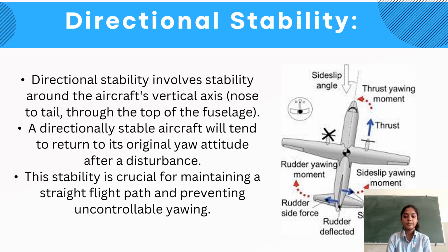To maintain directional stability and prevent the yaw from turning the airplane uncontrollably, the pilot deflects the rudder to the right. This creates a side force, countering the asymmetrical drag and the yawing moment from the engine failure. Directional stability ensures the airplane maintains its heading despite side forces or disturbances. In this case, the engine failure disrupts the symmetrical airflow of thrust, but the pilot's use of rudder demonstrates the importance of directional stability design features.